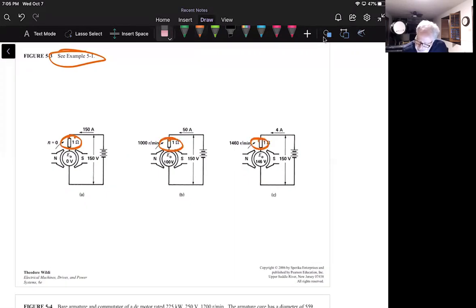Okay, and we can find that right here in these drawings of this DC motor that we're working at. That represents the armature resistance, the resistance that resides in those conductors. So it has a resistance of 1 ohm, and it generates a voltage of 50 volts when it's rotating at 500 RPMs.